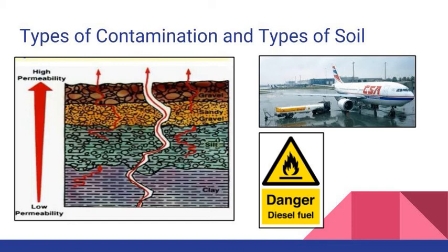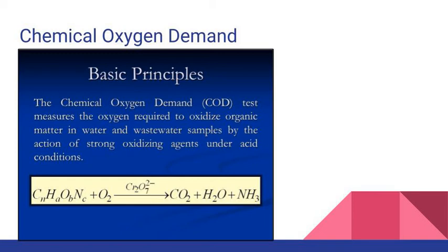Heavier petroleum products such as lubricating oil generally take longer to biodegrade than the lighter products. Although enhanced aerobic bioremediation technologies may still be effective, it is generally not practical to use them to address free mobile product or petroleum contamination in low permeability soil. In this picture here, we can see sandy gravel, and gravel would be suitable instead of clay because clay has lower permeability.